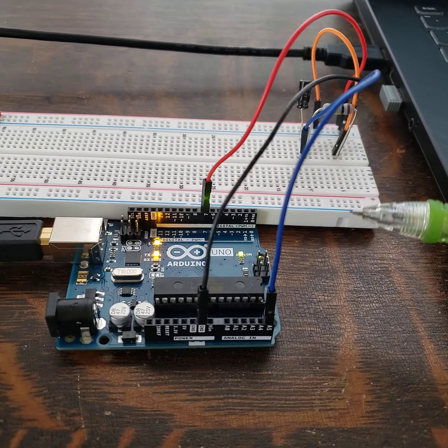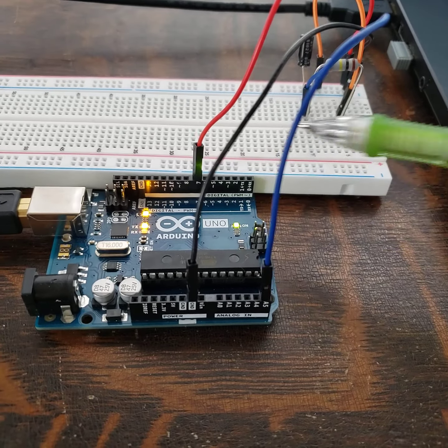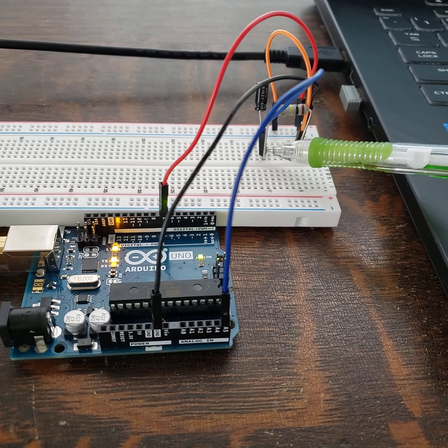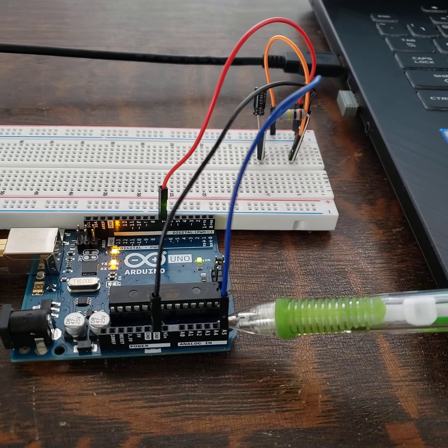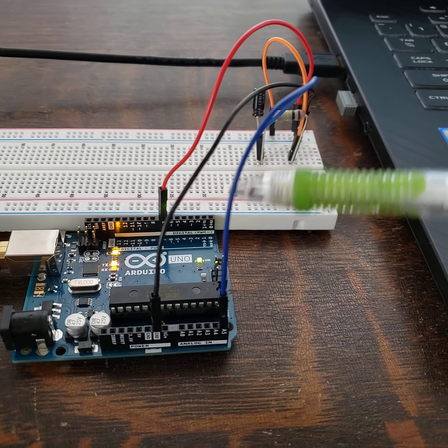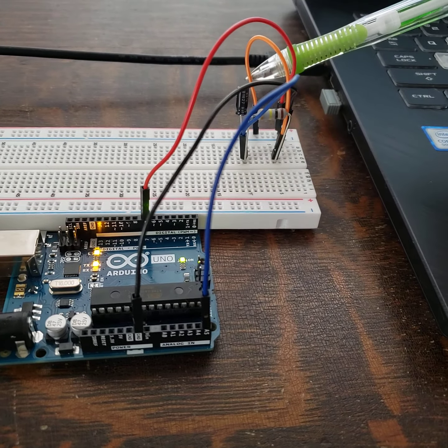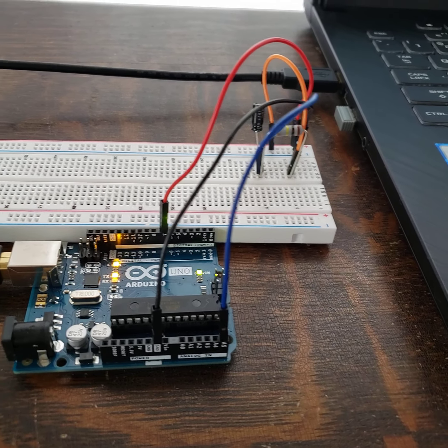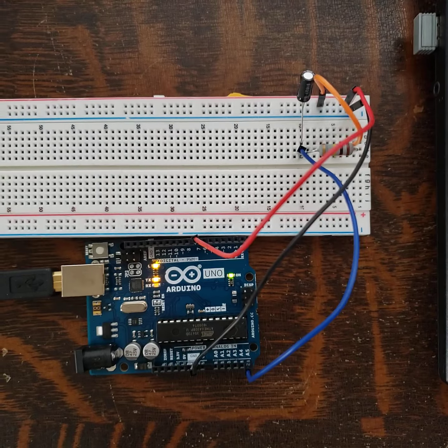Let's start off with the hardware. You see that digital pin 7 goes to the positive strip on my breadboard, which jumps to the resistor, which then jumps to analog pin 5 to record the data, and which is also connected to a capacitor, which is connected to ground. Better view of that. There you go.